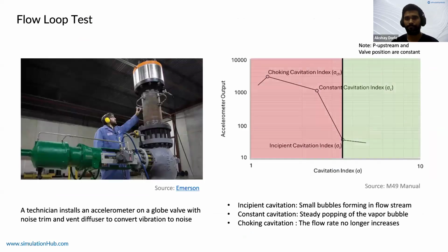Yes. So you see the incipient cavitation index. If it is less, then the red colored cavitating zone is also less. So when you want to compare two designs, you compare incipient cavitation index. If the incipient cavitation index is less, then the design is better, and the P minimum is more, and so on.